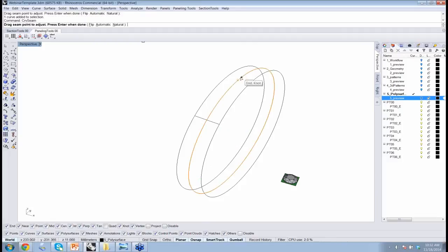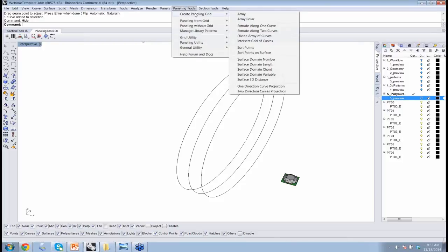I repeat the same with these. Now look at the seam here. The location of the seam was affected by the base geometry that I projected to. And this is why each one of these curves had a different kind of seam or a different starting point. And this is what messed up my grid. Now I moved all of them to this line. I'm just going to hide that line. I'm going to have a second attempt to create that array of curves.